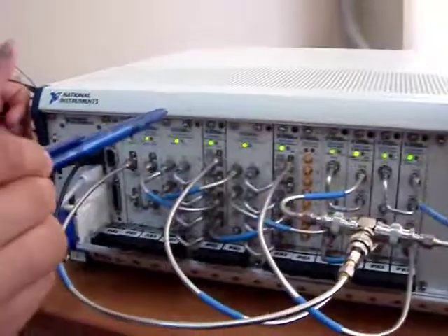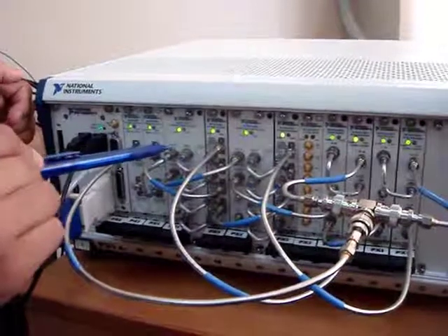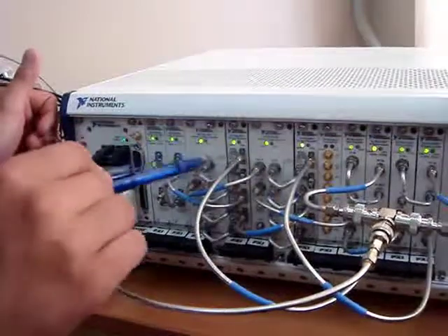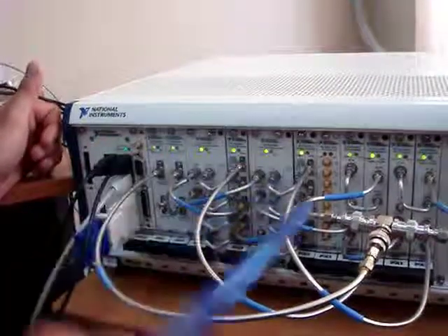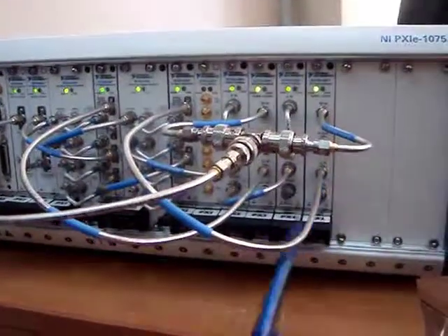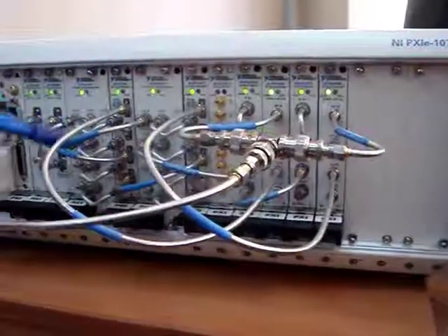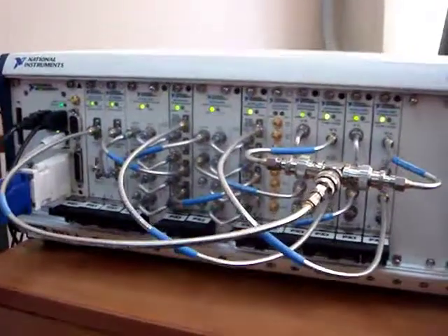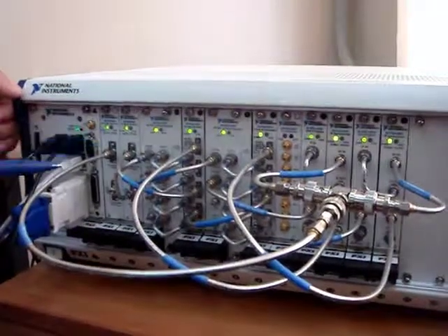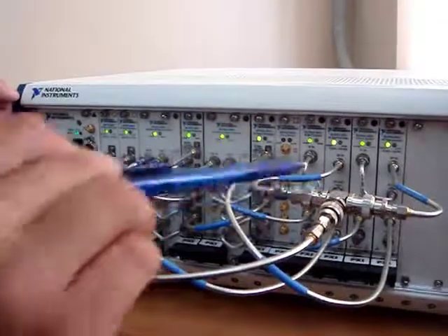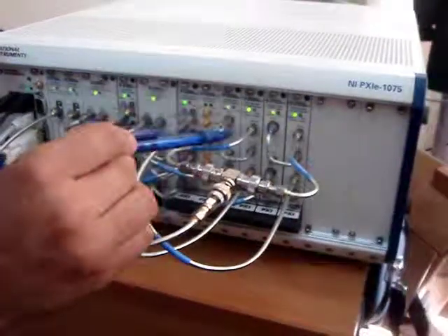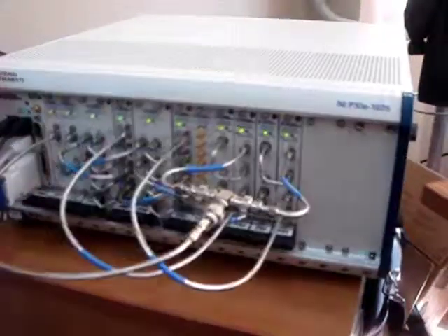After mathematical computation, we have 2 external LOs whose signals differ by 20 MHz. Outputs of these generators are connected to the inputs of our 2 vector signal analyzers. Of course, we have connected our synchronization part too. So from our singleton generation, from our probe signal, we have power division into 2 parts, and these 2 parts are connected to our vector signal analyzer inputs.